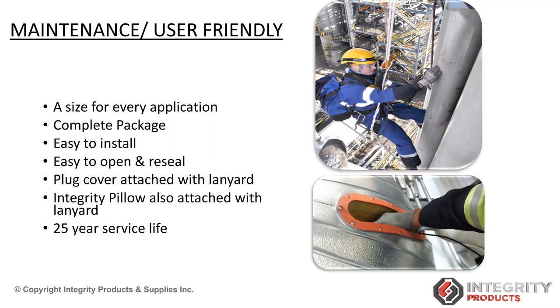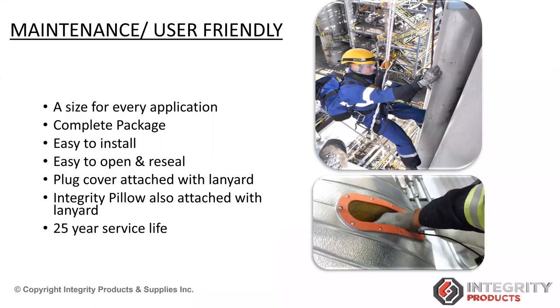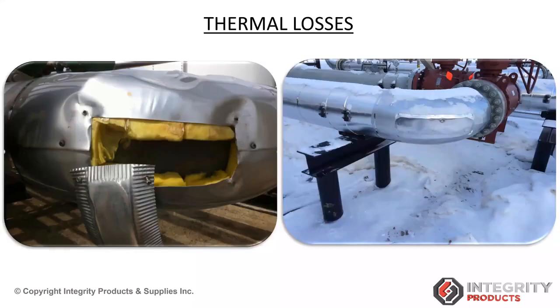Absolutely. And like I mentioned previously about the missing insulation, this sort of thing can easily be overlooked during even the inspection walkthroughs, especially when they're at those elevated platforms. Especially if it's covered up, like if the metal piece here has been put back in place, you don't know the insulation is missing behind it. Exactly. And also when they are making the punch items list, if it's on the elevated platforms, it can remain undetected. Yeah, for sure.